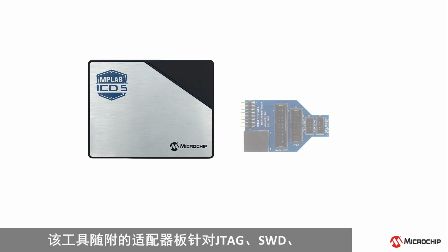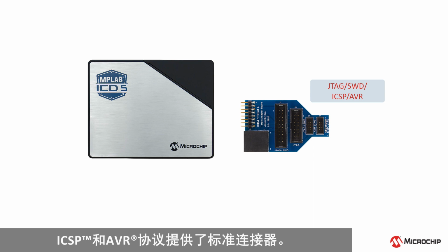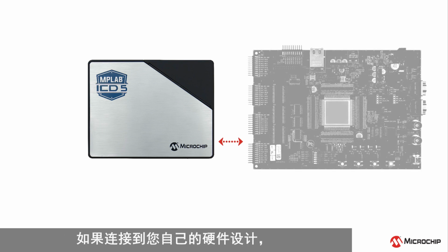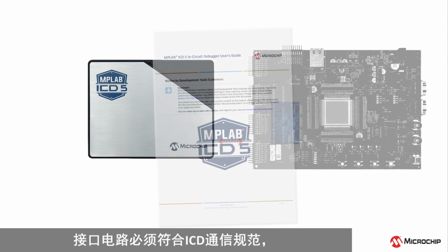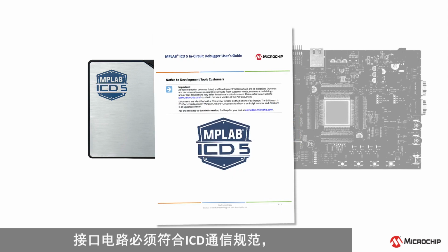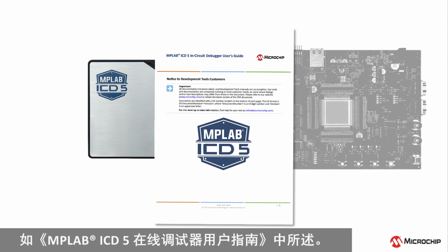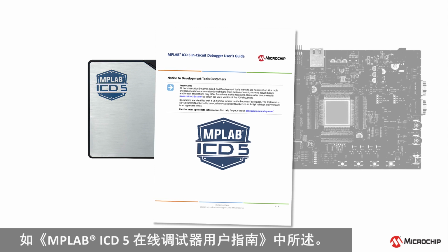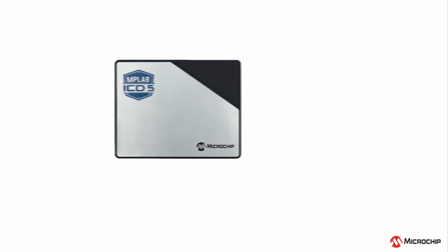An adapter board included with the tool provides standard connectors for JTAG, SWD, ICSP, and AVR protocols. If connecting to your own hardware design, the interface circuitry must meet the ICD communication specification, as described in the MPLAB ICD 5 in-circuit debugger's user's guide.